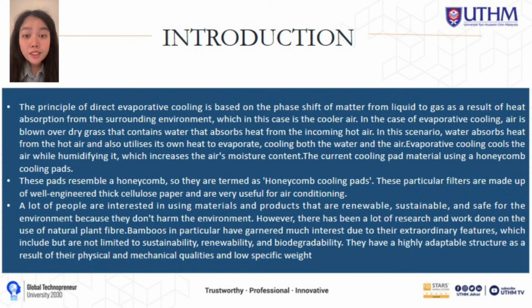In this scenario, water absorbs heat from the hot air and also utilizes its own heat to evaporate, cooling both the water and the air. Once the water reaches a constant temperature, all of the heat from the evaporation is absorbed by the incoming hot air, increasing the cooling rate of the air.